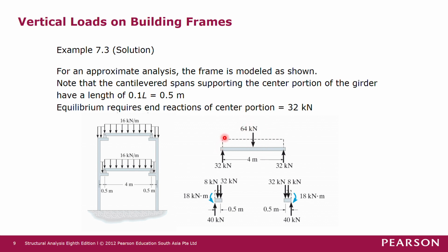We just look at this uniform load initially. And then for this simply supported beam, there should be vertical reactions at the pin joint there, and supposedly there should be a horizontal reaction, but we assume that this girder does not support axial force, so the horizontal reaction is 0.